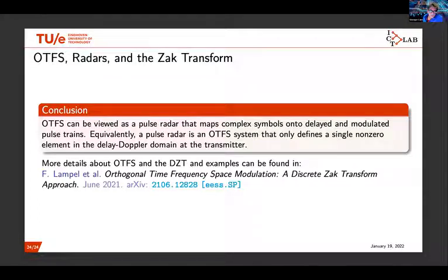If you can afford the complexity and you can do maximum likelihood on the whole frame with all known symbols, then this is the same. As long as the duration and the bandwidth are the same, you can even see from the Cramér-Rao bound that the properties of parameter estimation are almost identical. We have done the Cramér-Rao bound with OTFS, OFDM and chirp, these compressed waveforms. As long as you integrate over a certain duration and the bandwidth is the same, the Cramér-Rao bound is almost invariant to the waveform.